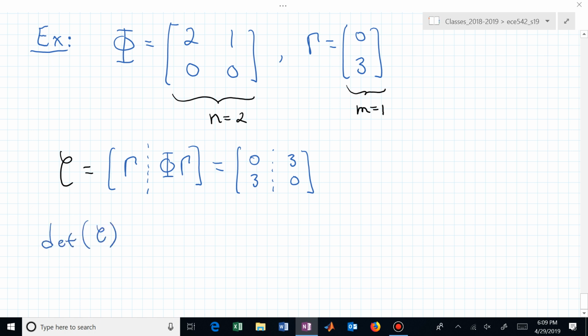Since it's square, since we had one input, little m was 1, we can check to see, and hopefully you can see visually that those rows or columns are linearly independent, and say, oh, this system is controllable because we have this controllability matrix C is full rank. It has 2 linearly independent rows. They're not a linear combination of each other.